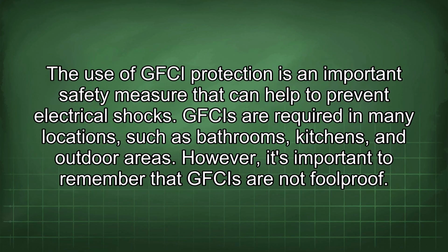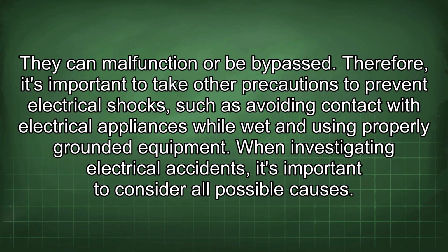The use of GFCI protection is an important safety measure that can help to prevent electrical shocks. GFCIs are required in many locations, such as bathrooms, kitchens, and outdoor areas. However, it's important to remember that GFCIs are not foolproof. They can malfunction or be bypassed. Therefore, it's important to take other precautions to prevent electrical shocks, such as avoiding contact with electrical appliances while wet and using properly grounded equipment.